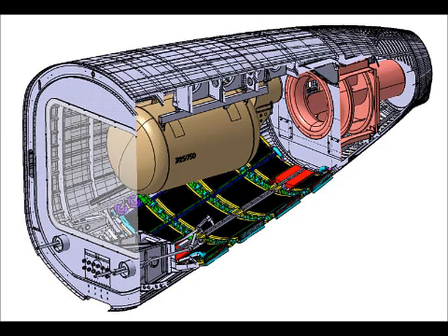As SOFC APU is a relatively new technology, conventional turbine APU is still more affordable for airlines to adopt. SOFC APUs are still currently both bigger and heavier than traditional turbine APU of equal output. In order to achieve wide acceptance of this young technology, the SOFC APU needs to be more affordable as well as to support higher power density. But with more resources and focus being placed into the field of fuel cell research and development, it is only a matter of time before we overcome these challenges.